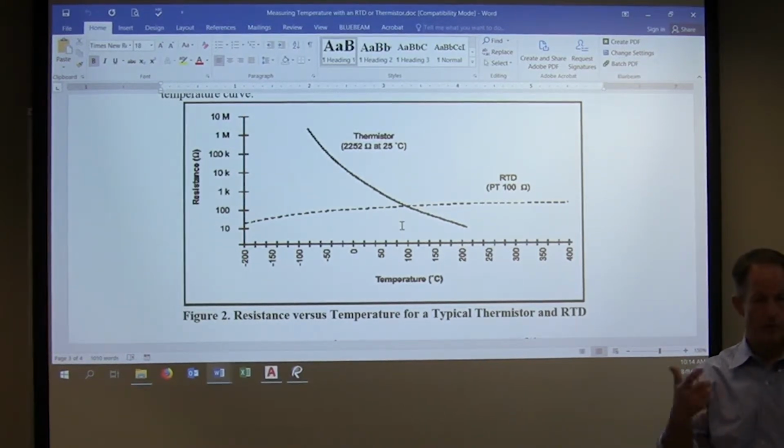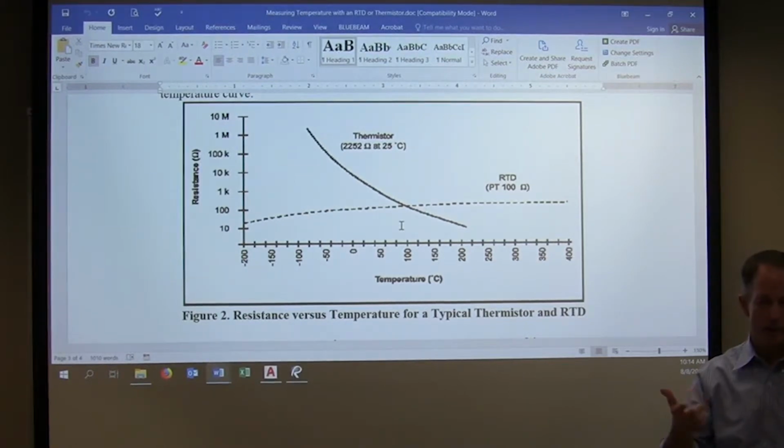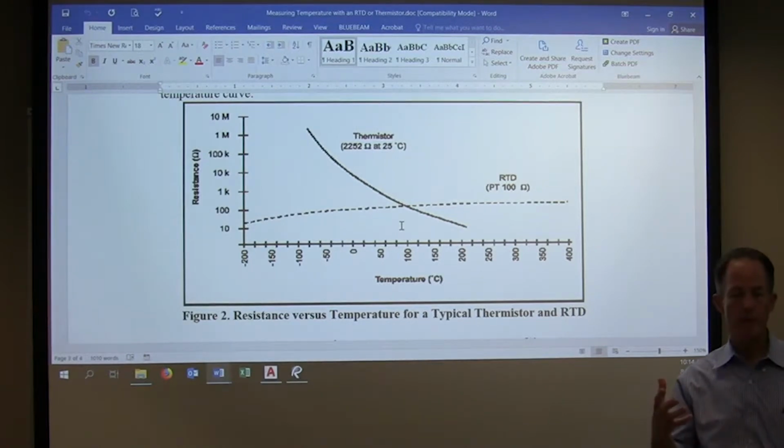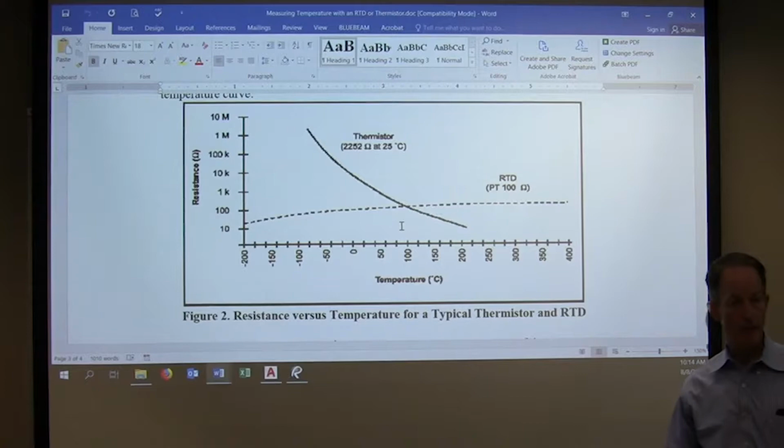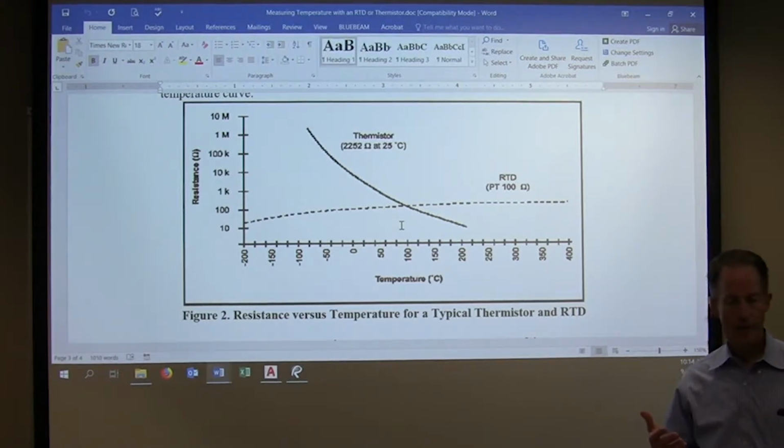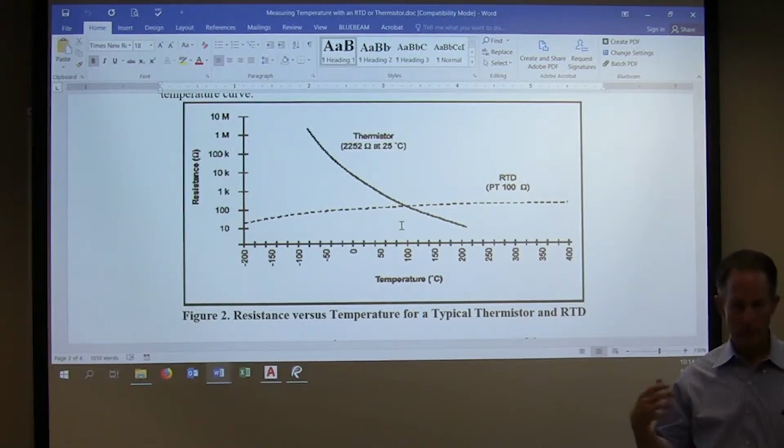So you've got pressures, you've got flows, whether it's airflow or water or some other liquid. Humidity sensors, okay? Those sensors are typically measuring the relative humidity in the space, and what do they send us? Do we get a resistive, voltage, or a milliamp signal? It changes it into an electronic signal, right? Typically it's either a milliamp or a voltage. So all of the sensors that we work with basically come down to this voltage, current, or milliamp scenario. So we want to spend a little bit of time talking about Ohm's law.